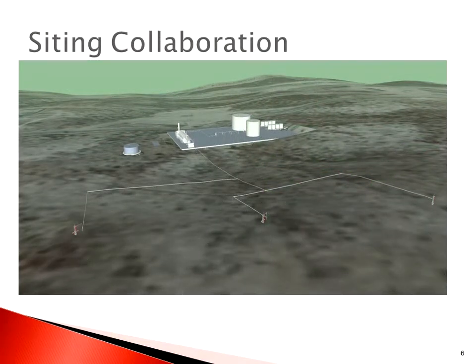First, we will collaborate on locating the facility. We will consider a clear location that is central to wells, not under major power lines, accessible from the roads, close to tie-ins, and will not receive runoff from other areas. After that, we will field verify the locations, checking for buried obstructions, and then select the best site.